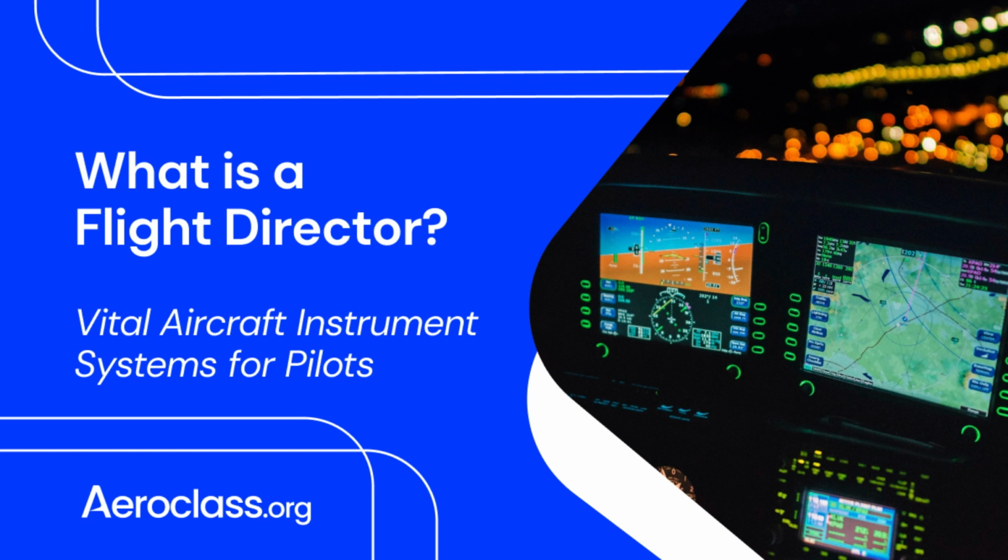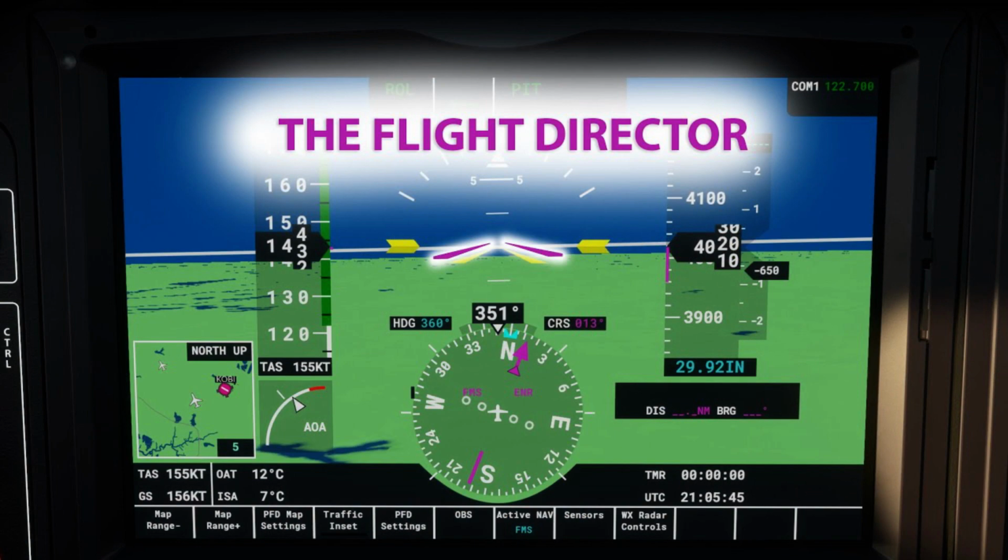Most flight directors accept data input from the Air Data Computer, ADC, Attitude Heading Reference System, AHRS, navigation sources, the pilot's control panel, and the autopilot servo feedback, to name some examples. The downside is that you must program the FD to display what you are to do. If you do not pre-program the FD in time, or correctly, FD guidance may be inaccurate.